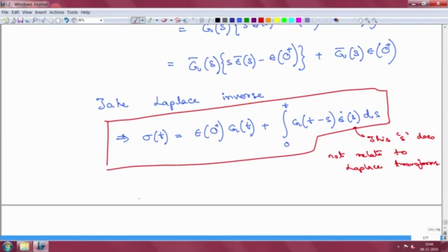So, this shows that this particular equation is more fundamental in nature, and it is not really related to the models and the particular model that you have chosen. And you can show this, that this is generally applicable to the case of linear viscoelasticity, right. So, just like what you have for the stress given an arbitrary strain history, you can rederive the case of the strain for an arbitrary stress history, right, when we flip the two.